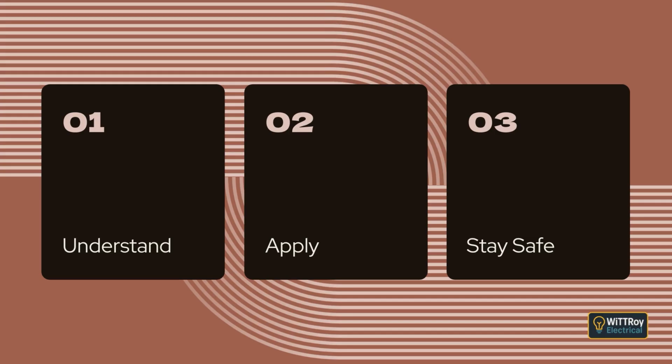Clause 2.5.7, Reliability of supply. Clause 2.5.7 is all about keeping the power on as much as possible when something goes wrong. The idea is simple. When we design an electrical installation, we don't want one fault to shut down the whole place. So the installation should be divided into sensible circuits, and each circuit should have protective devices chosen and set so they work together properly.